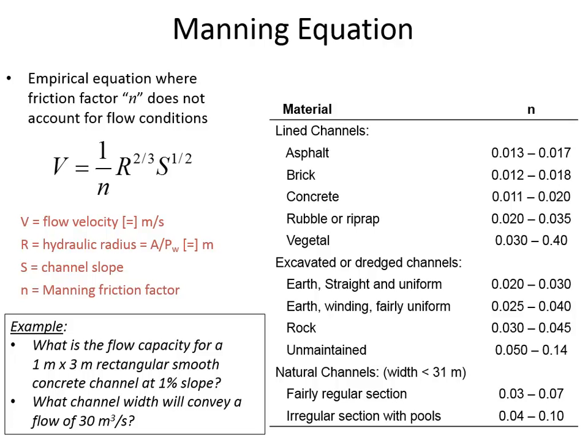That approach doesn't work because, remember, our flow resistance is a function of how close we are to the surface that's imparting resistance. And so if you make it wider, there's more flow area that's far away from the channel sides, and so it doesn't scale linearly. And so this shortcut approach doesn't work.